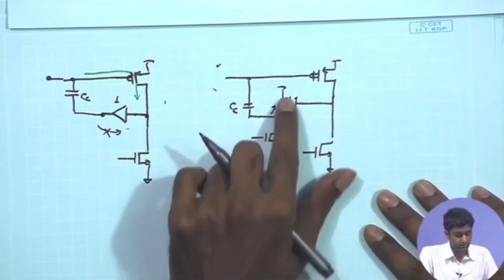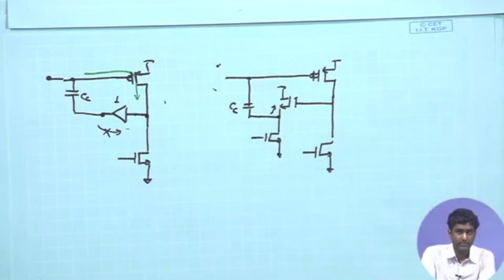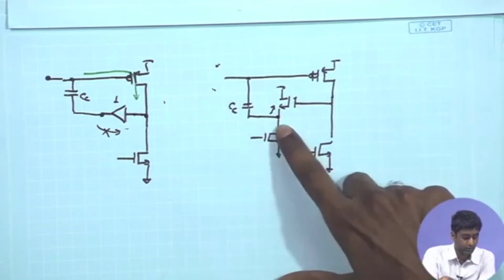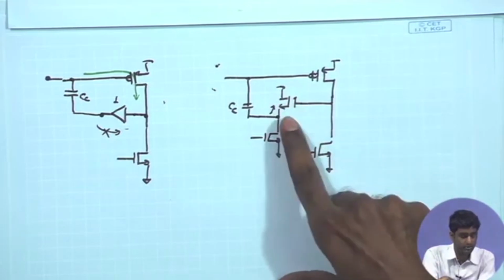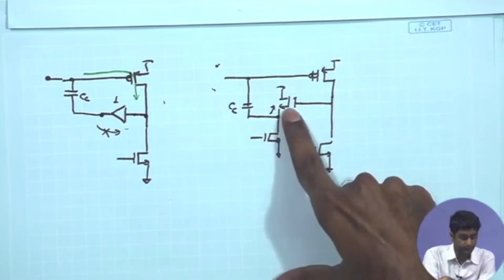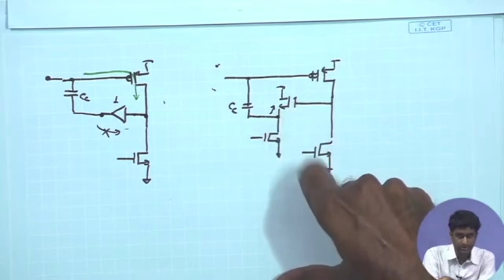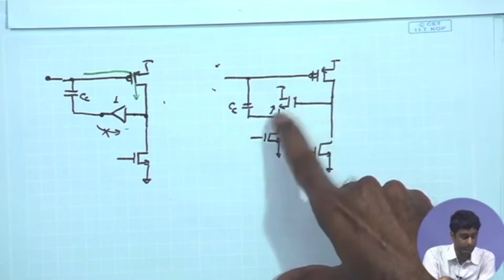But once again, when we are trying to incorporate this stage and trying to make the output impedance lower, it is going to add additional power consumption in this particular branch, because it will need sufficient bias current to have a large gm. So, that the output impedance of this stage is sufficiently low and it is acting like a good common drain buffer.